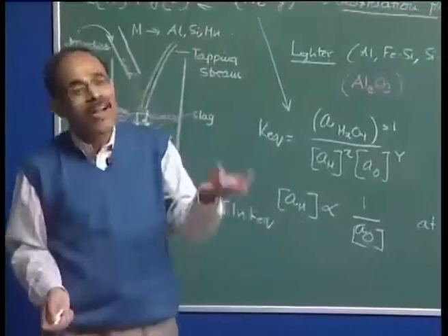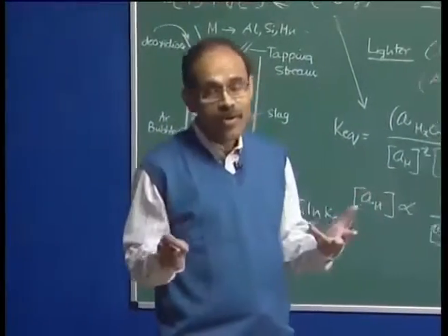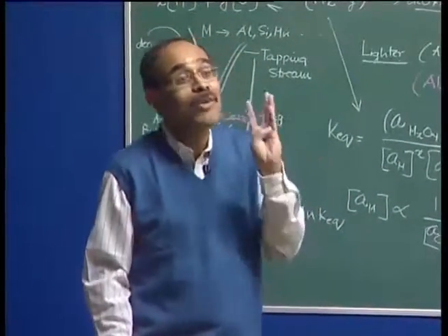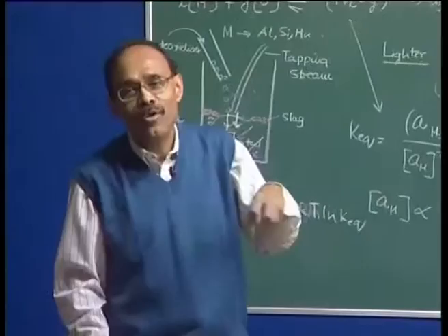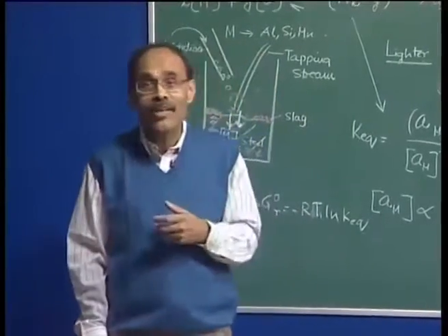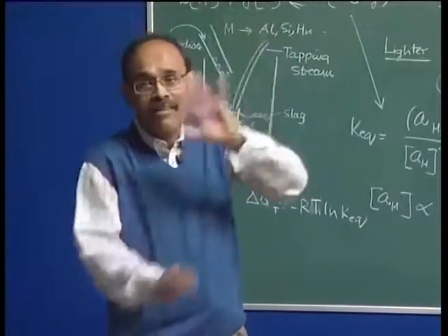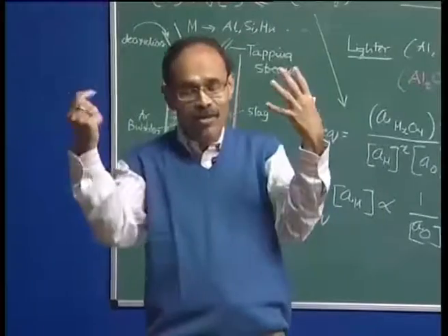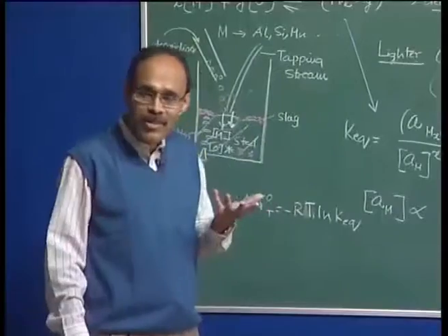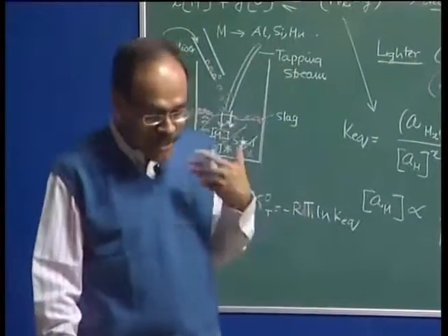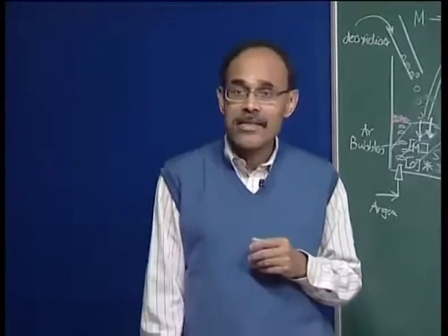We have solid deoxidation product, liquid deoxidation product, and gaseous deoxidation product. Solid is not wanted as far as possible, but we see that aluminum, which is such a powerful deoxidizer, which gives low residual and can bring down oxygen to a very low level with only a little contamination, unfortunately forms a solid deoxidation product. And we want the final steel to be devoid of these deoxidation products, which, as we will know later, are called inclusions. Contamination of steel with deoxidation product is referred to as dirty steel. An associated subject is cleanliness control, and so on.